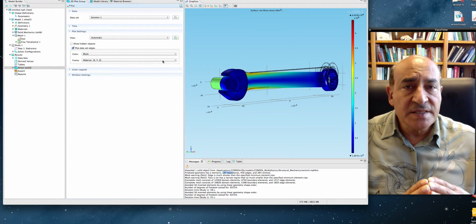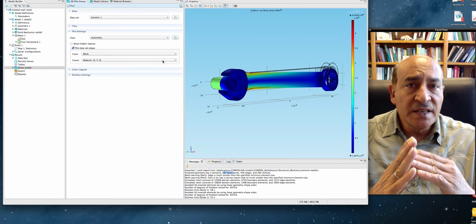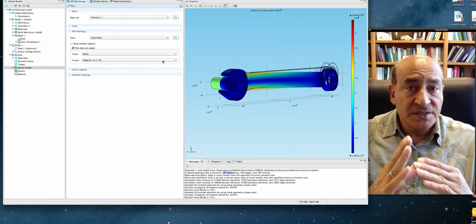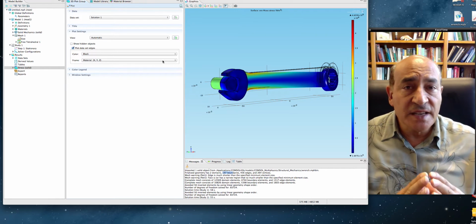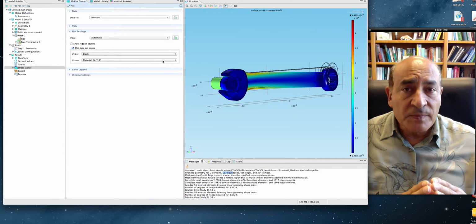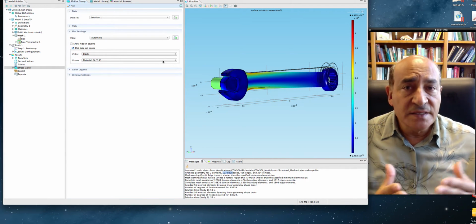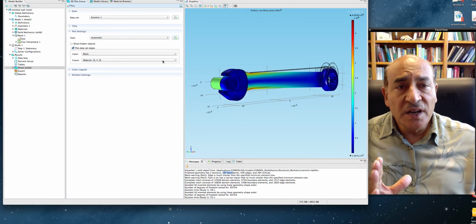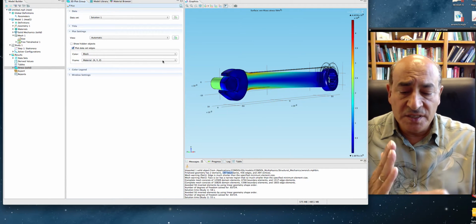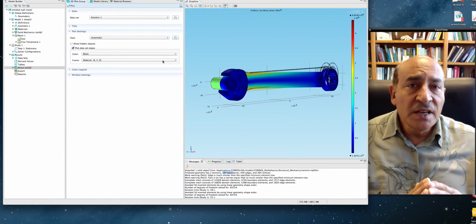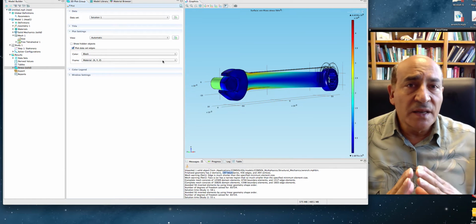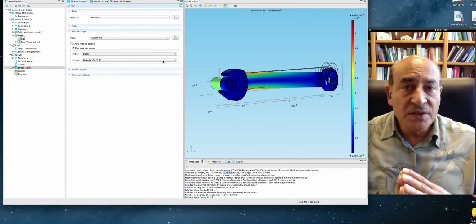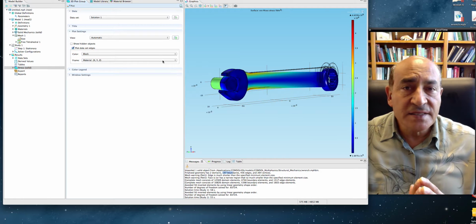What it does is assume a deformation field, a displacement field, inside the pyramid, either linear or quadratic. These are called shape functions, and based on that, it produces equations for the nodes of the pyramid. So this node here, and this node here, and this node here. These equations are the displacements for the nodes, the strain, and also the stress.